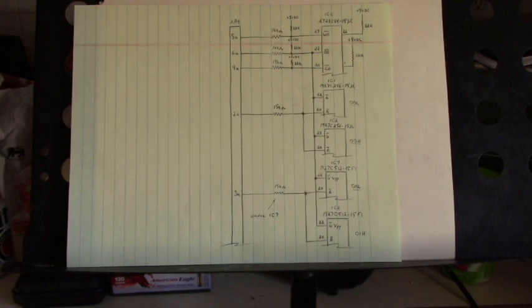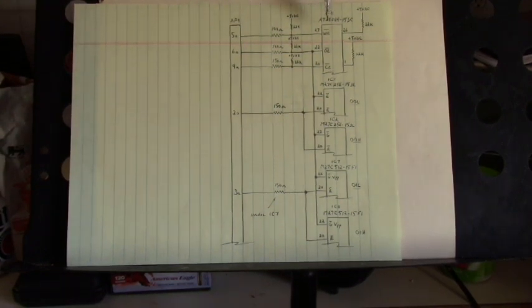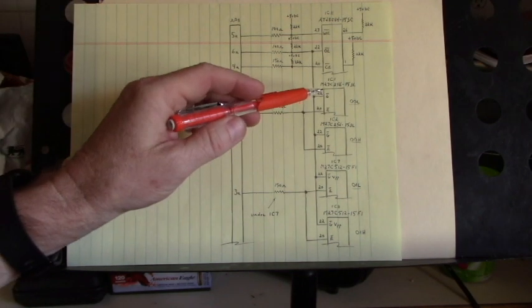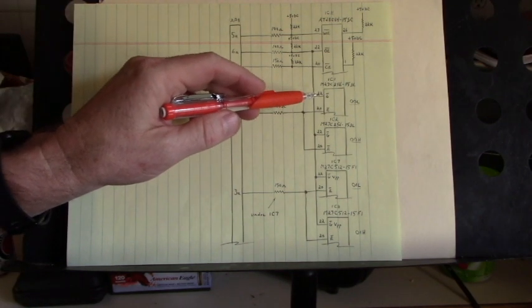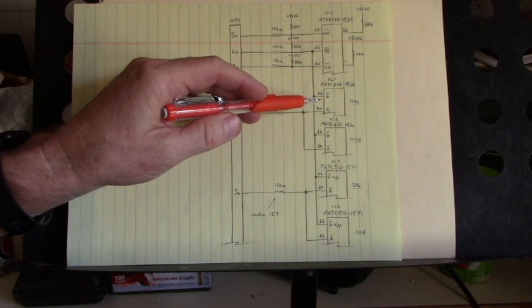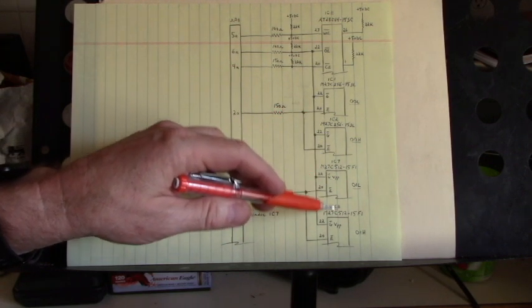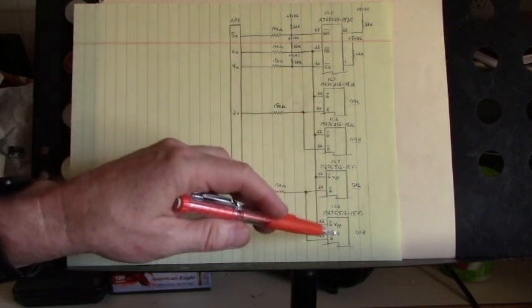Now here is the write enable. This is read write. It's read when it's high, write when it's low. Here's the output enable, and here's the chip enable of the AT28C64. Now down here are the output enables and enables of the EEPROMs, and we're not worried about that.